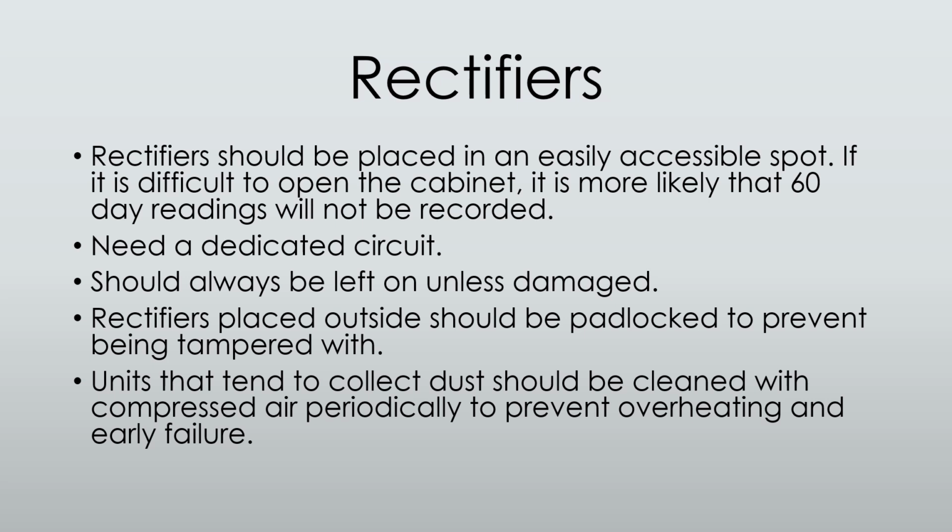Rectifiers need a dedicated circuit. It should always be left on unless damaged. If there's a short, if there's electrical damage that's visible, call a technician, get it checked out. Rectifiers placed outside should be padlocked to prevent being tampered with. And we talked about the possibility of the wires being switched. If the polarity is switched, you can cause damage to your tanks very quickly. Units that tend to collect dust should be cleaned with compressed air periodically to prevent overheating and early failure.